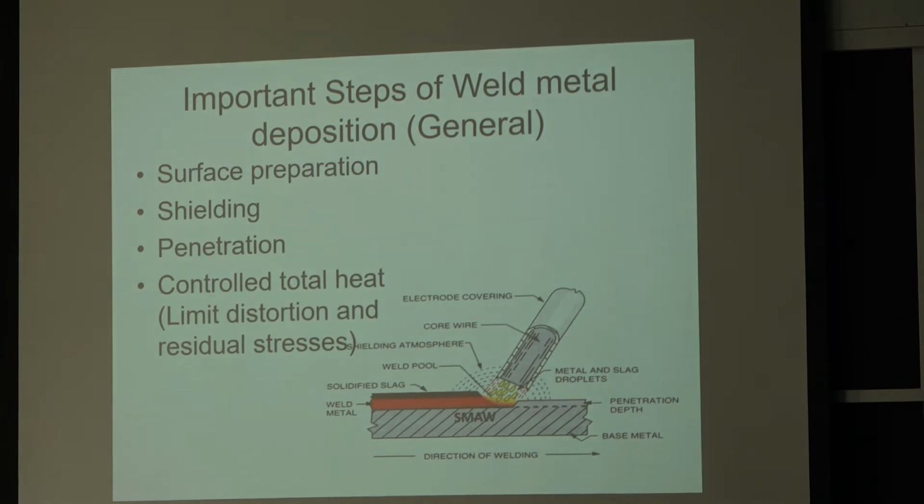Okay, we'll talk a little bit more about what happens when, with enough training, you take a welding machine, and you come with an electrode and you arc against the surface. So there are a couple of things you do need to do: you put the ground on the part. That's how you get the current to go through and create the arc. The arc is going to melt both the base material and your welded electrodes. We're just talking about the very, very basic welding process, and I'll expand to what happens in other situations.